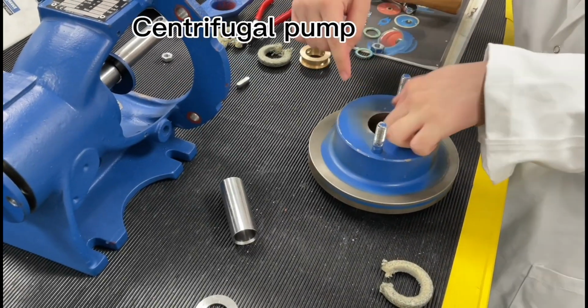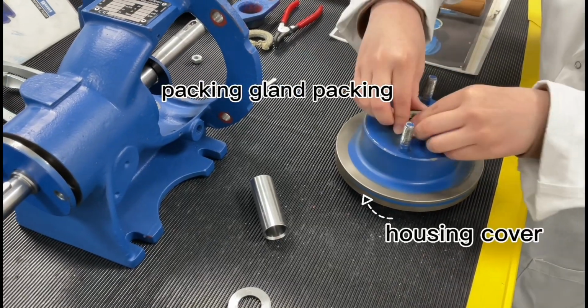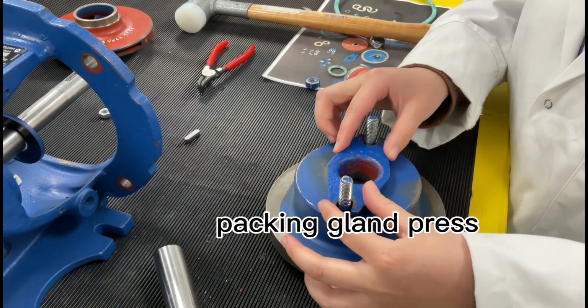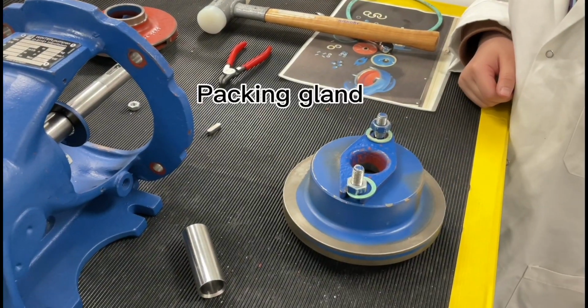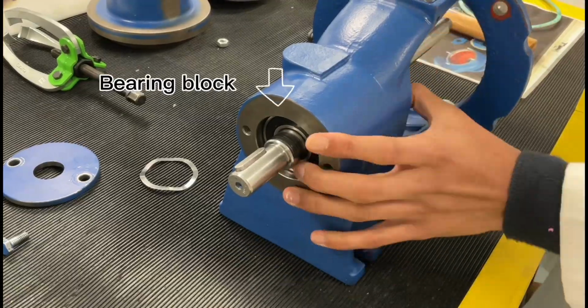For the centrifugal pump, 1 circle packing was put in the housing cover followed by the locking ring and 3 more circle packing. Put on the press and on the top of it, put 2 washers and tie them with a nut. This whole unit is called packing gland. After that, insert the shaft with radial ball bearing into the bearing box.